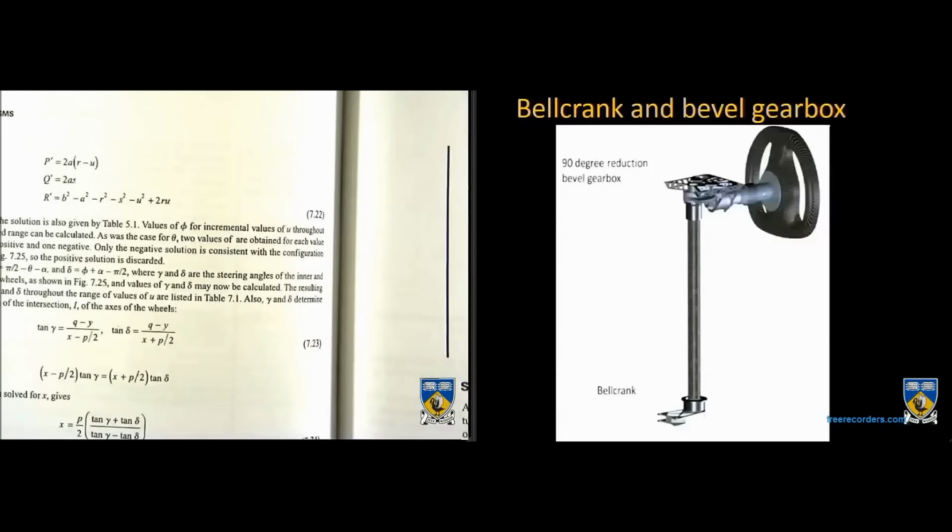Next up is the 2009 design, I think this one is. So up the top you've got quite a compact bevel gearbox in there. It's quite neat because you don't have a steering column running all the way down to the car, and if the driver is sitting in front of the car, you can have the steering column go essentially right between his crotch. Whereas the other one you're looking at, it's going down towards your toes, so it takes up a long packaging room. And then at the bottom, you've got your bearing support and your bell crank, so you can already see that it's quite simple in supports.